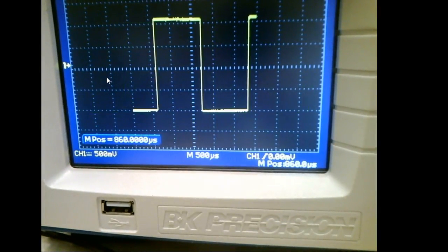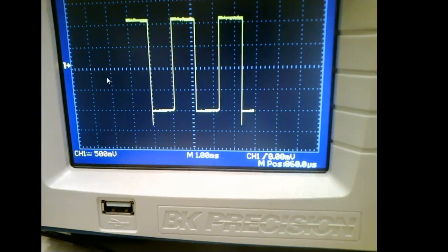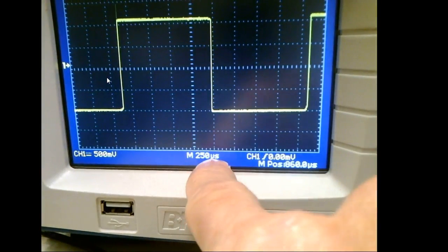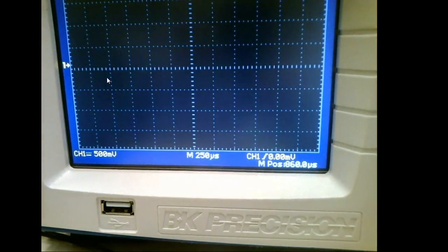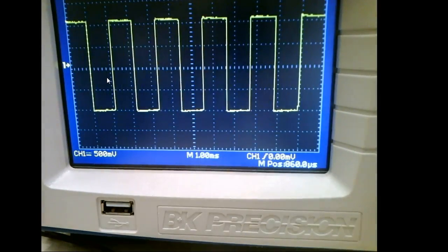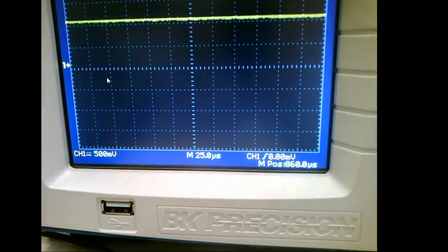If I go right here, then my scope is less accurate because I'm trying to put too much information inside of a single division. So my ultimate goal is to set the speed of my scope, which is in time. If speed goes up, time goes down, right? So notice if I go to the left, my scope goes slow. If I go to the right, my scope goes faster. Now, of course, it looks to me like DC, because my scope's got the high spread out over more than the scope can see.